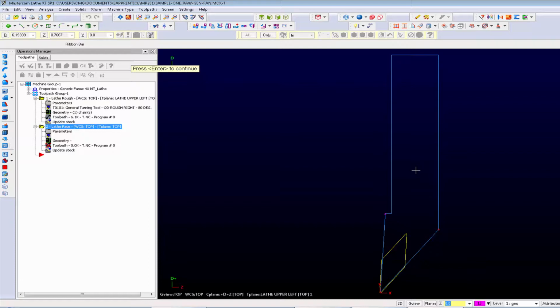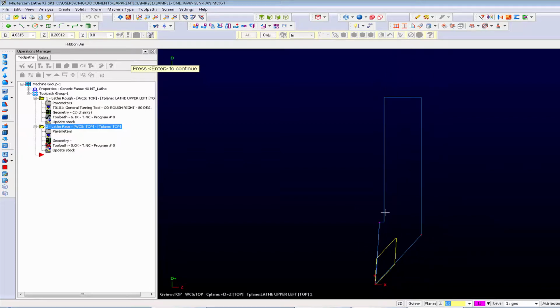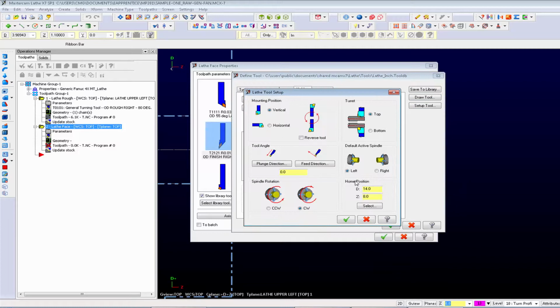Got a question from Corey. Can you explain the difference between the yellow and orange inserts? Absolutely. Yellow indicates that that insert is facing up. So the body of the holder, when we're looking at this thing, is below the level of the insert. The orange insert is facing down. That's insert down direction. And you'll notice that this doesn't show the orange insert, but what it does is flip the holder around and not show you a picture with the blue, the light blue, and the yellow, because that's indicating that our insert is facing down.